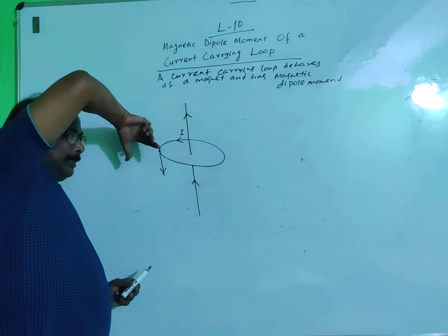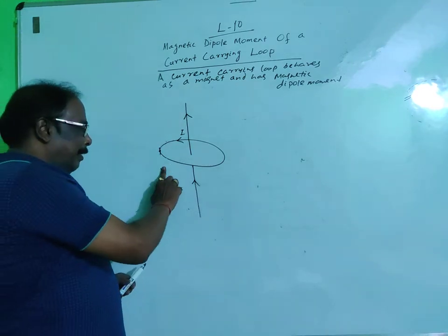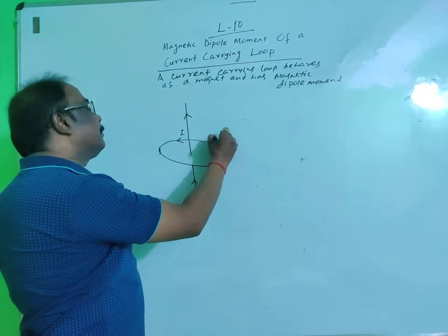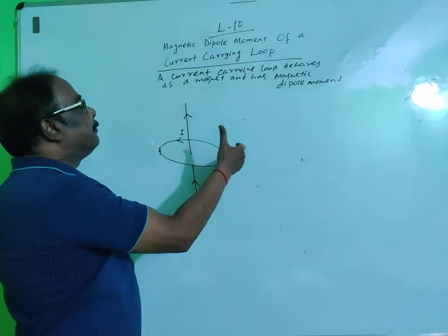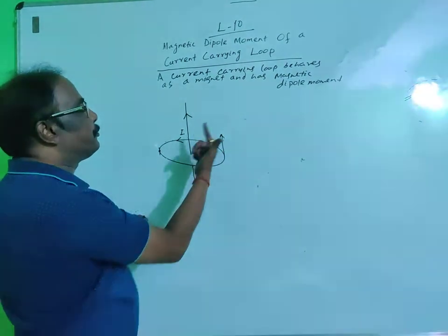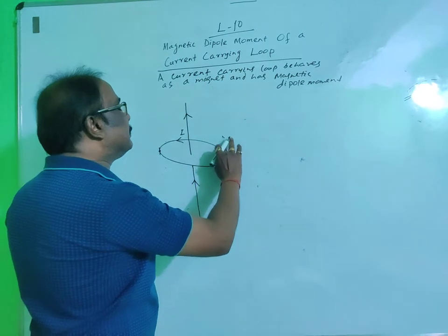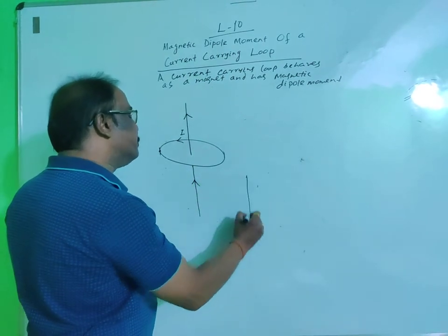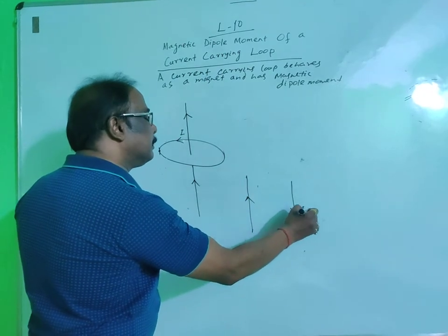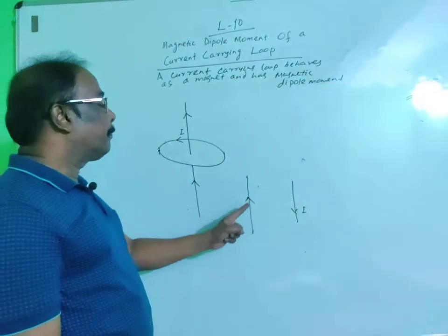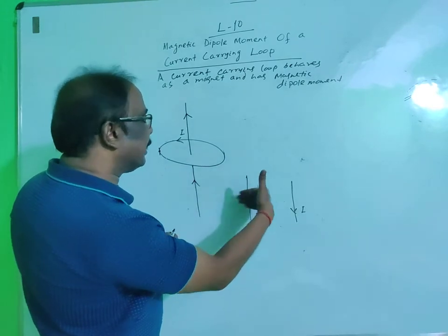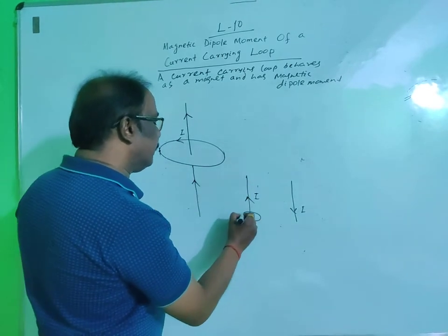Then this will represent the direction of the magnetic field in circular form, and here the direction of current will be upward. Again we can determine the direction of magnetic field lines around this, as we have represented in previous lectures. If you take current direction upward and here current direction downward for a straight conductor, then magnetic field lines can be represented in anticlockwise order.